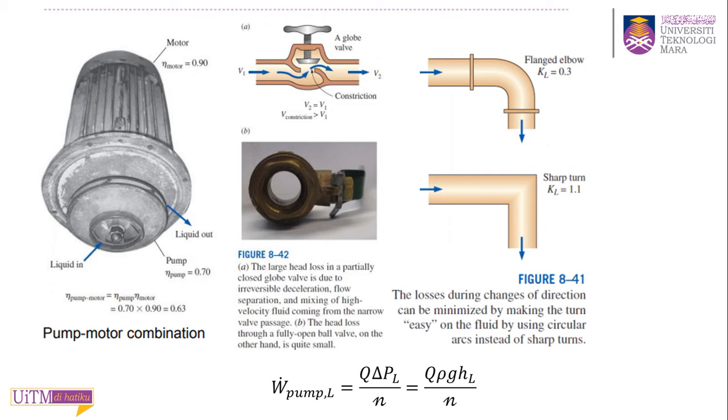Alright, so any pump or any motor, there will be efficiency. They are not working at 100% efficiency. They always have some friction or losses, so normally it has an efficiency of 0.7 or 0.9. So in a question, if they give you that information, working at an efficiency of 70% or 80%, 50%, depending on that question, we need to take into consideration that efficiency.